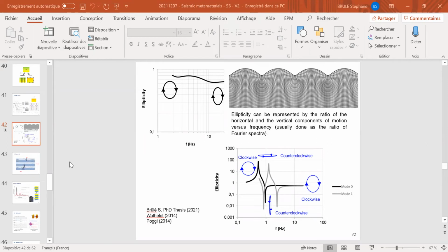I can't say that it is easy to do. What I am simply explaining is that we have to take into account all the complexity of the wave when we have modified the medium. So this is not only a shear wave modification profile, it could also be the frequency dependence of the Rayleigh waves. Okay, I see.